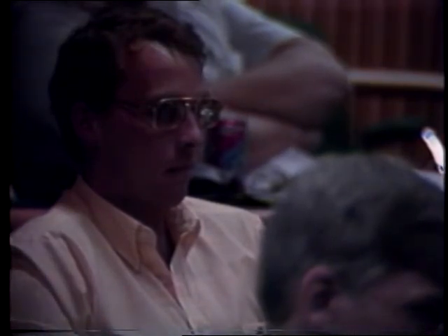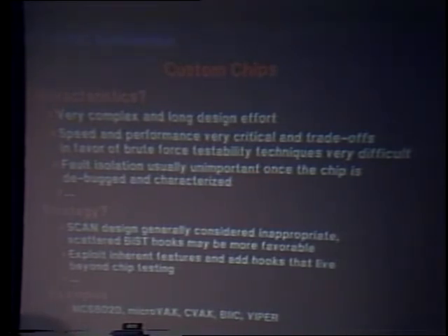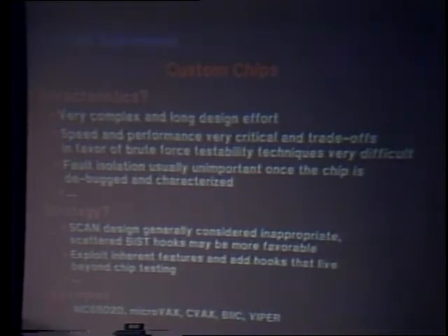Okay, what about the custom chips? Well, what are the characteristics? They are very complex, requiring long design effort, and speed and performance are so critical that applying any brute force testability is very difficult to justify. Also, I mentioned that fault isolation is usually unimportant once the chips have been characterized and in the mature production stage.